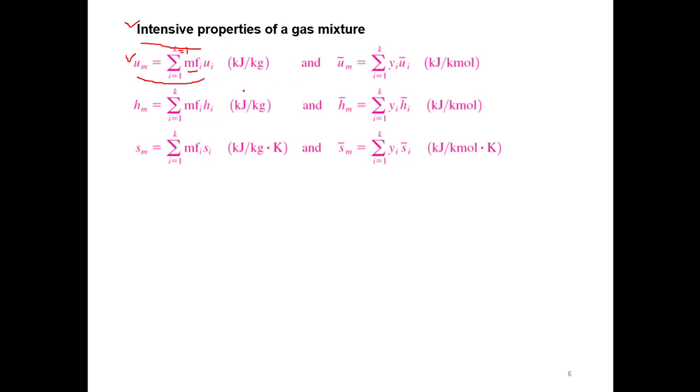And if these properties are available per kilomole instead of per kg, then instead of the mass fraction, you have to multiply with the mole fraction. The same applies for the enthalpy and the same applies for the entropy. They are the same.